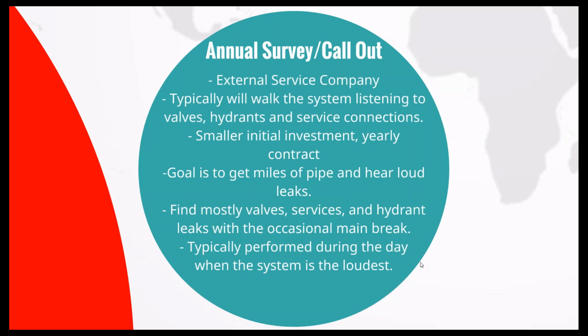And so the goal of this is to get through miles of pipe and hear leaks, and then deploy crews to address those leaks. But finding valve issues, service issues, and hydrant leaks, and occasionally you'll be able to pick up some leaks in the mains.